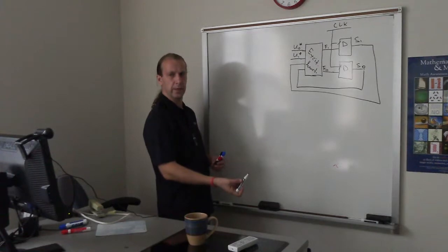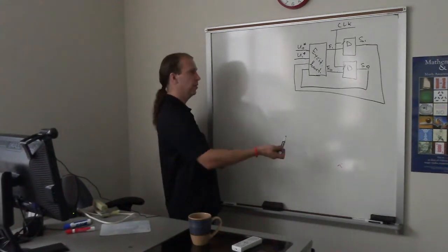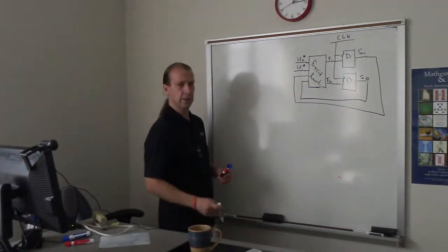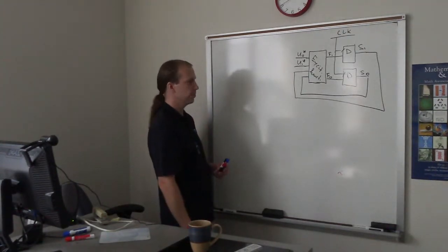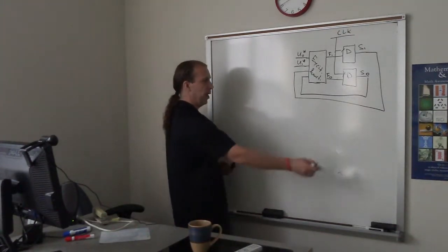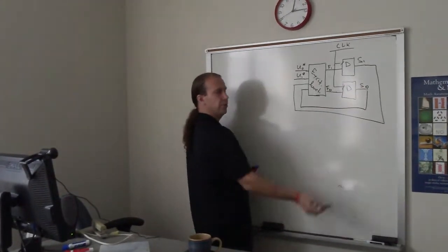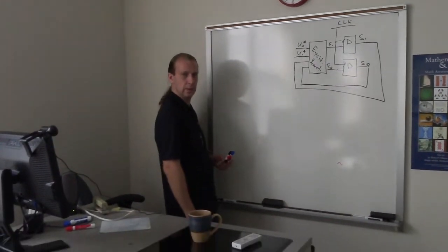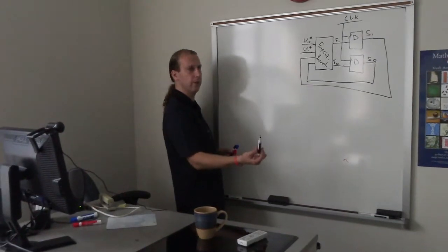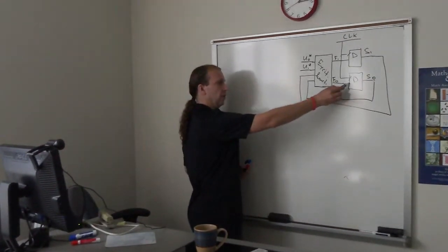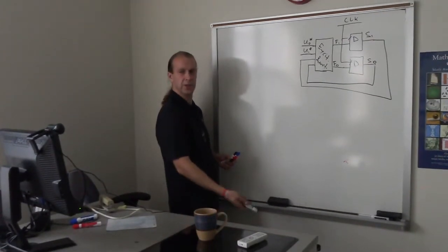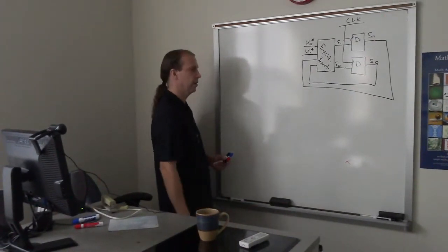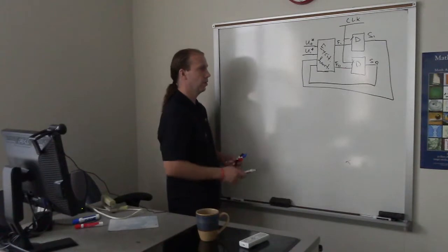It makes the delay until after the rising edge is here. So that's why we call S0 the previous. F0 will be something that will change the state, but the change will take place only when the clock comes.